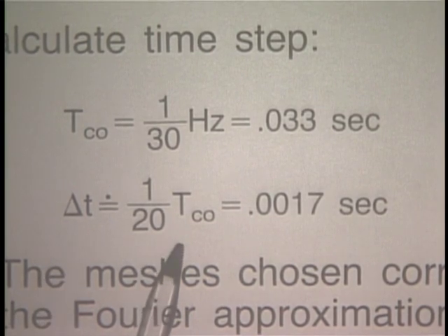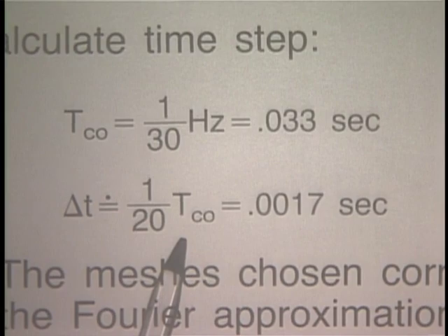and then we can say that the mesh up to 17 Hz represents the frequencies quite accurately, and we have integrated the frequencies up to 17 Hz quite accurately, and therefore we have an accurate solution of the problem up to 17 Hz.